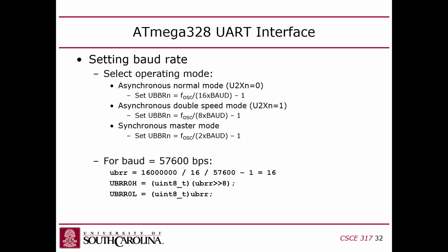They call it baud instead of kilobits per second because kilobits per second is a little misleading. You've got the start bit and the stop bit and the parity bit, so there's some overhead. So you're not actually getting 57.6 kilobits per second throughput of data, because the baud is how fast the signal switches physically, including all of the overhead bits that are required as part of the protocol.